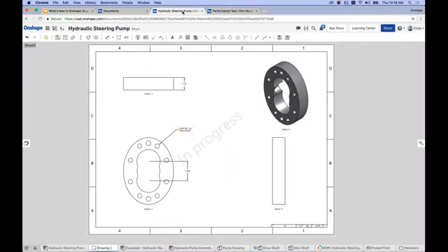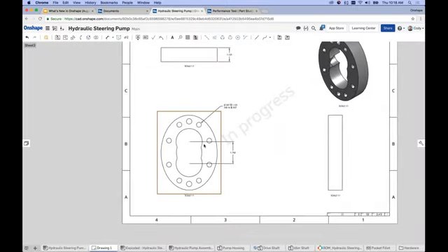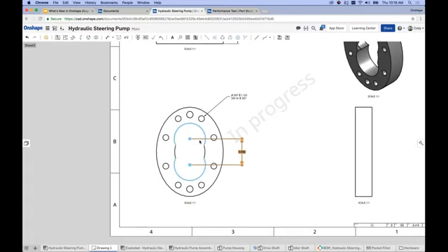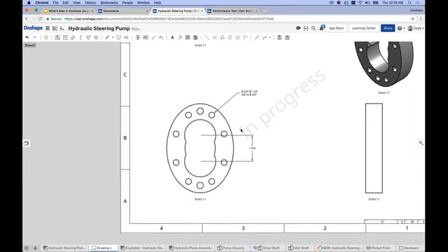The next thing I want to mention is the MinMax Dimension improvement, and this is especially important if you find yourself dimensioning to the outside of arcs or the inside of arcs very often. And the trouble could be when you try to drag the dimensions to those points.